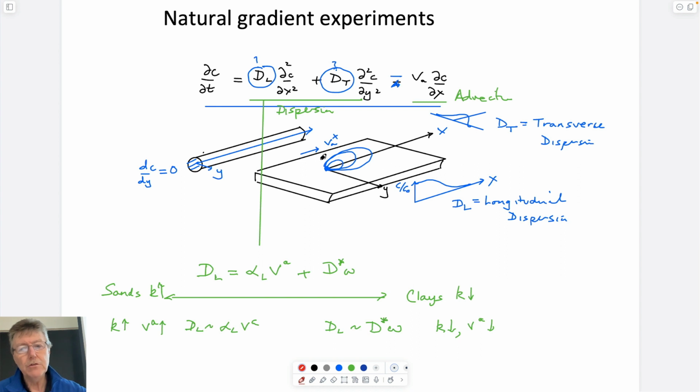We know that in this 2-dimensional case, since the box that's containing our contours is getting larger as we go downstream, the same mass of fluid in this larger box will by definition be a lower concentration. The transverse dispersion causes this bell curve effect if you look at a cross-section perpendicular to flow. If you look at a cross-section along flow, then it might look like this if you keep the concentration at the source constant, or it might look like a bell curve as it goes downstream if you don't.